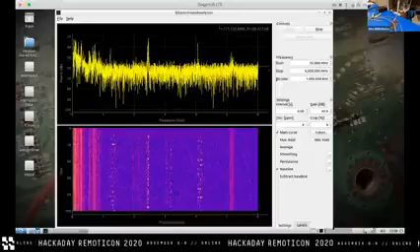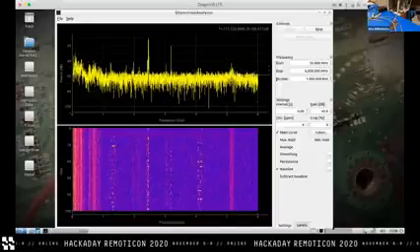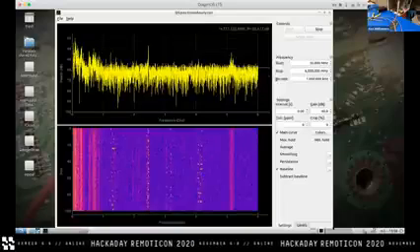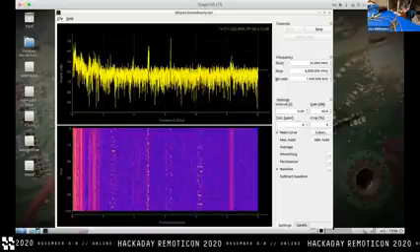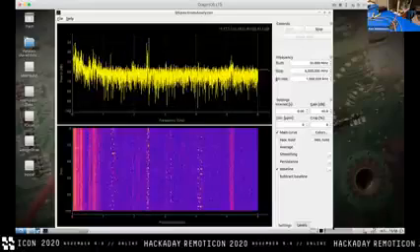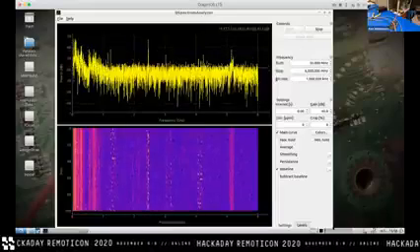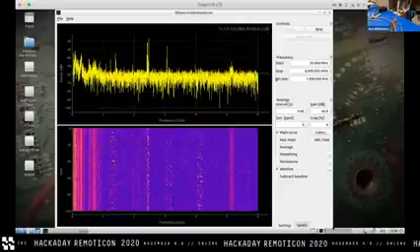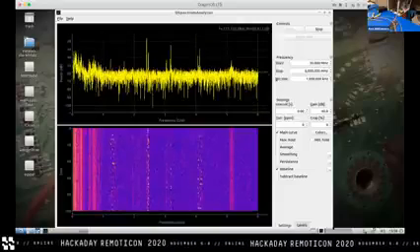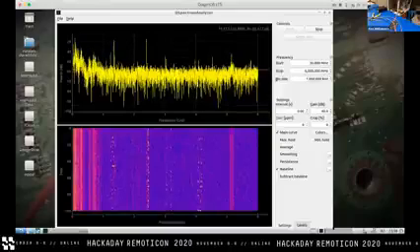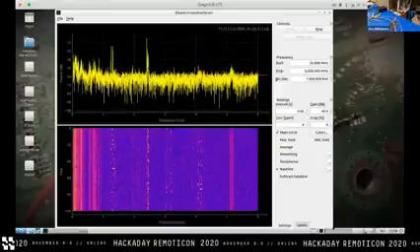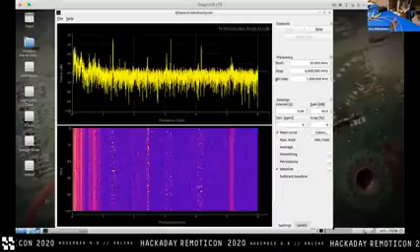On the other hand, if you're building your own connected hardware and leaving DIY antennas out of it, you can probably characterize all of that stuff reasonably well with a NanoVNA or something like that, to the point where you can get an at least calibrated, if not necessarily accurate, measurement setup. So if you're 10 dB below the limit or something like that, you are pretty confident at that point it's good. No, I haven't tried it though.